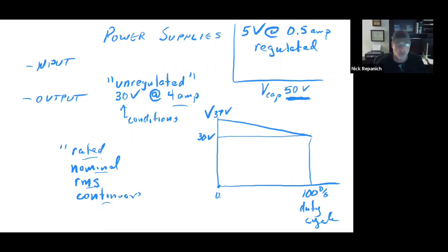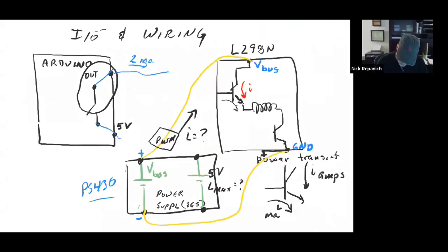Wiring connectors. What I don't want you to ever do is just grab 2 wires and twist them together and put a piece of tape on it. You can do that with the loads. You can do that with these kind of resistive loads. You can put a piece of tape on it, and if it comes off, it stops current flowing and it's no big deal. Except now you probably have one conductor that has power on it and it starts running around.